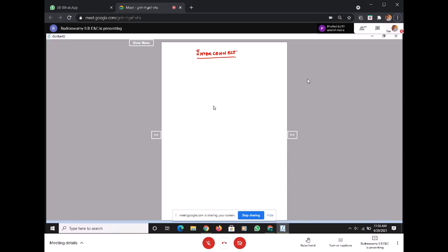We defined two terminologies. One is the wire pitch. What is wire pitch basically? It is the width of the wire plus the spacing between the two wires. So this is what the wire pitch is all about.